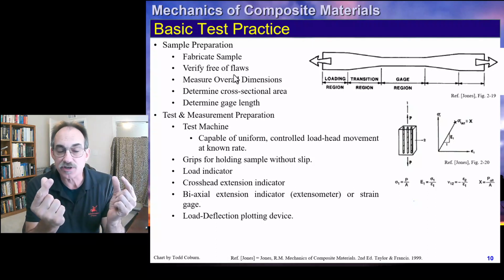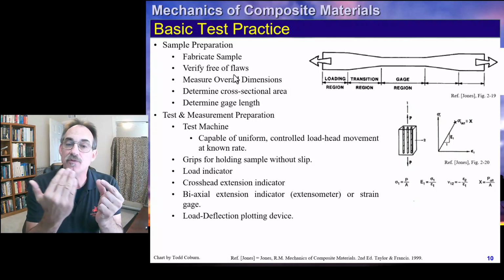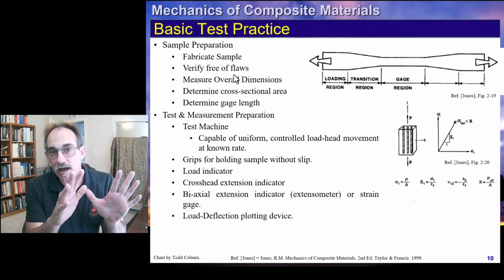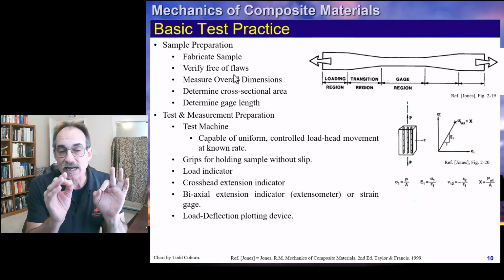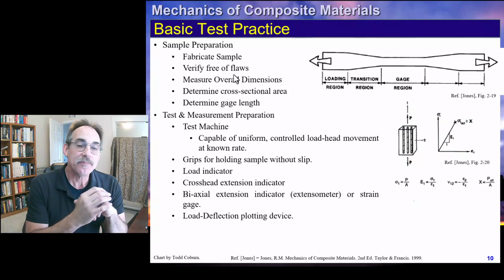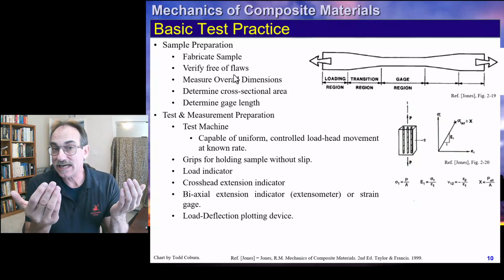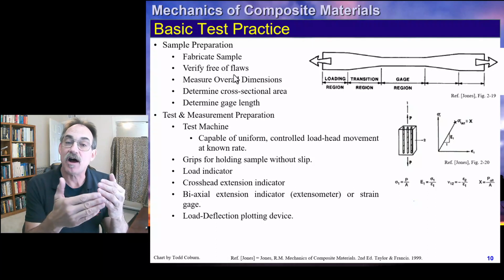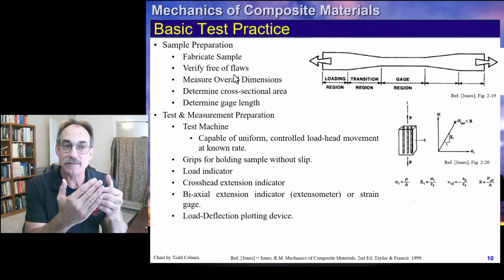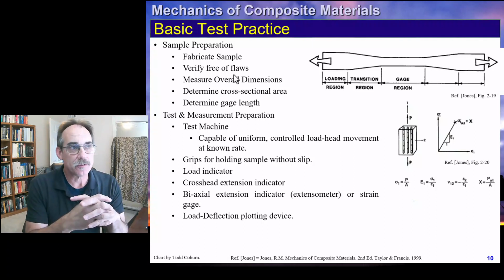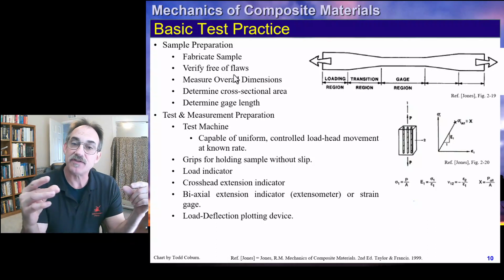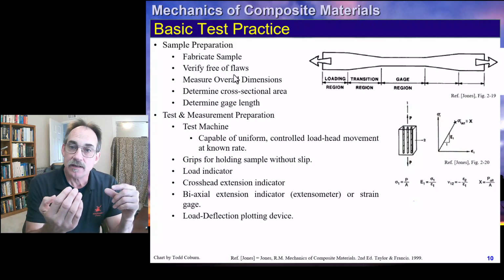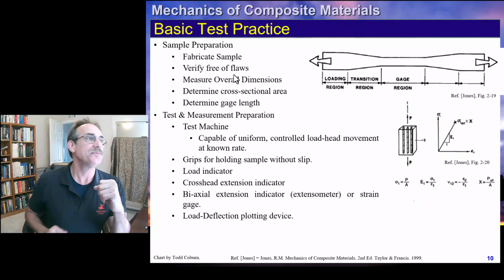When you have these samples, they're a lot smaller, so any kind of issue from cutting the sample can adversely affect your results. So you want to cut carefully with the right kind of saw, the right kind of blade. If we have a wet sample, a lot of times we're going to try not to drive off that moisture, and so what we'll do is cut it wet with a wet saw so that it doesn't drive off the moisture. Also, a lot of times we'll have someone sand or polish the edges of the sample so you don't get any stress risers from the cut edge.